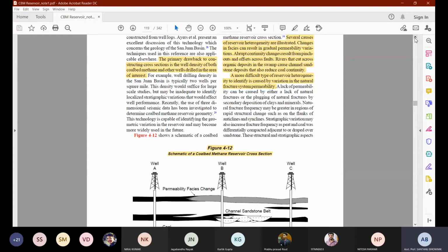So now, going back to a rock mechanics class, considering the chapter on stresses around mine excavation, you all have studied how the radial, tangential, and differential or shear stresses are going to vary at the boundary, and we have also considered the distance as you move in the lateral, horizontal or vertical direction from the center of the excavation. Now this excavation size may be rectangular, square shaped, rounded corner, circular or elliptical.